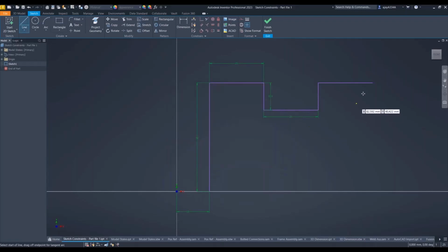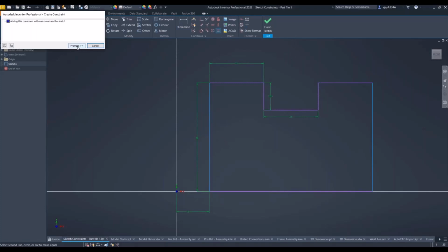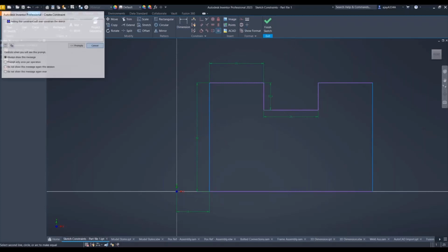What we can do is draw this line, and as you'll see, it freezes, and you can see the icon next to the cursor showing that we are looking at a perpendicular, or rather a vertical, line. Then to equate it, you would pull that coincident constraint there and define it. At this point, you'll see that the sketch currently is not completely constrained, and I'll tell you why. Let's do this constraint. If we make that one equal to that one, it says it will make it over constrained. Then you say cancel, it's fine.